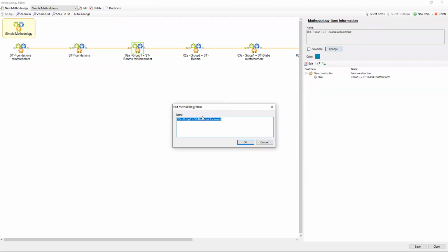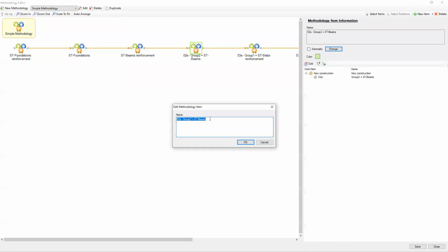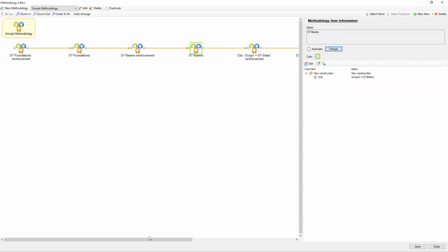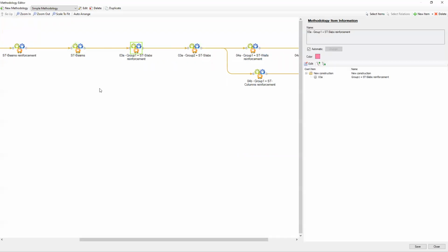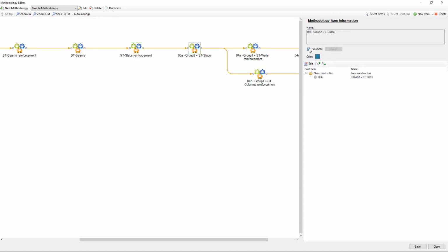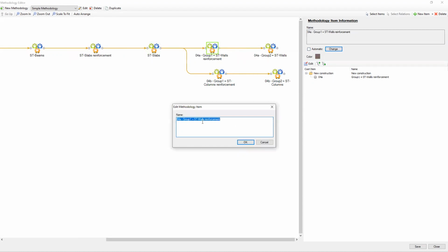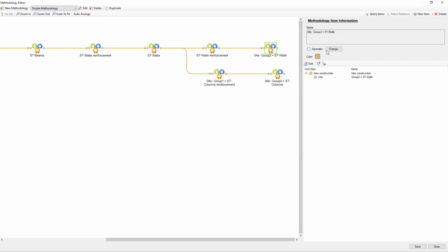and so on. I'm just gonna quickly try to rename these, but I think you can catch what the process is. First, you link your cost items to your tasks, and then you create your relations between these tasks, and then you can use these options to rename these tasks if you find it more understandable for the project.